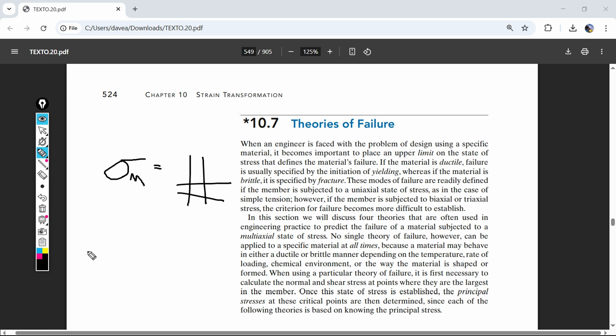And then when we did the shear, we say that's tau. And tau is still that force, those opposing forces, or the force divided by the area. And just like axial tension is the force divided by the area, it's the actual axial tension or compression, and that's going to be sigma. So hell yeah, we have these two equations.